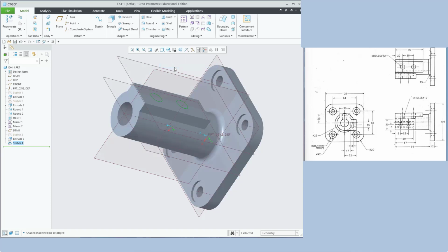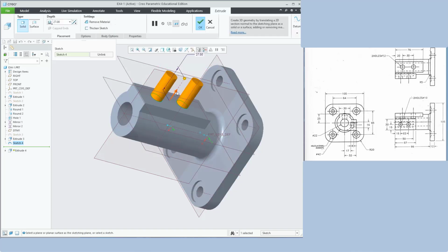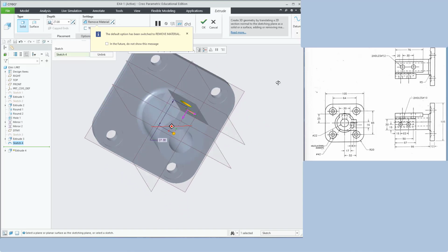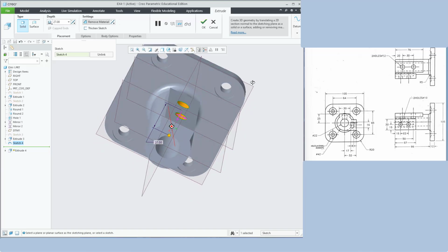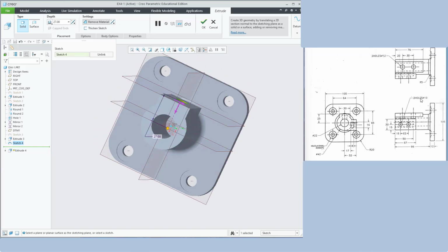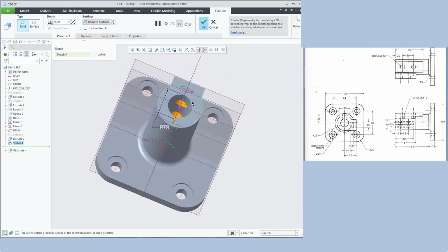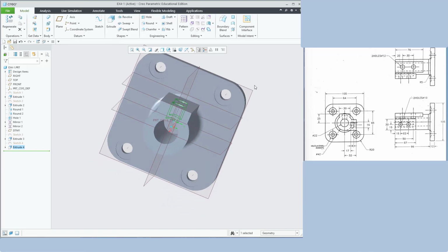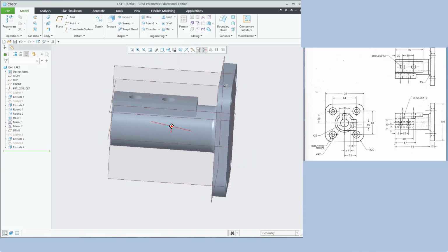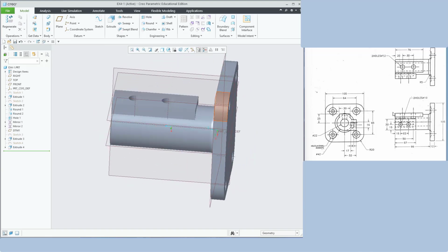Go to shading view. Go to extrude. Change the direction. It is a hole up to maybe even this center or up to this distance you can give. Okay, it is coming up to the center, or maybe this dia we know, this distance we know, it is 25. So maybe you can even give up to 25 or even lesser is fine. Okay, it should reach this surface. That's all. This distance is enough. I give 25 and finish it. This completes the top portion.